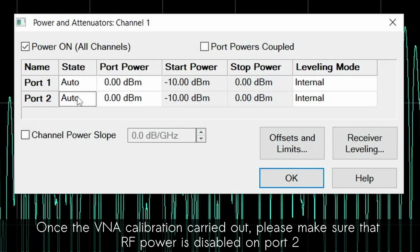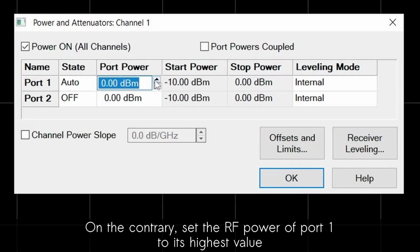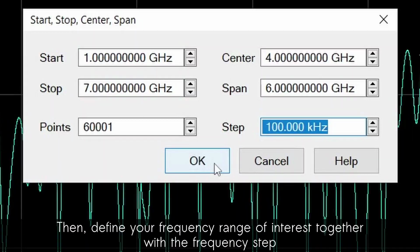Once the VNA calibration is carried out, please make sure that RF power is disabled on port 2, otherwise you may damage the output stage of the optoelectric converter by direct injection of RF power. On the contrary, set the RF power of port 1 to its highest value. Then, define your frequency range of interest together with the frequency step.